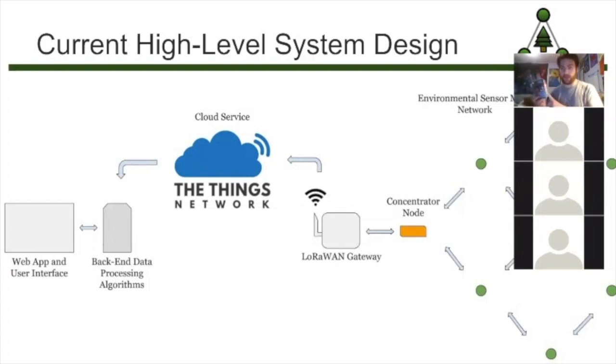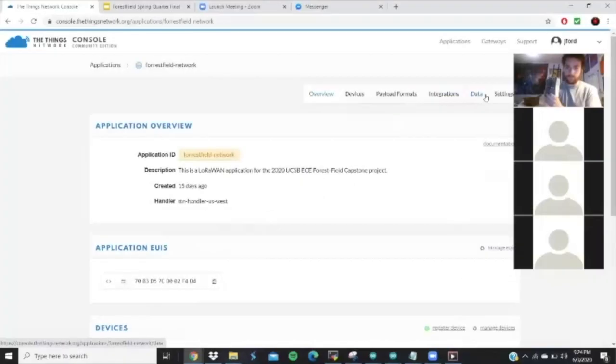This node that I'm holding in my hand is a concentrator node and has multiple lights attached to it. The blue light indicates that it is receiving data from one of the other nodes in the network. The number of flashes indicates the node ID, with the red light indicating if the mesh network is functioning properly, in that data is being transferred from one node to another node and then from that node to the concentrator, thus having a multi-hop network that is indicative of a mesh network. The concentrator takes the data off of the mesh network and uploads it to the TTN.